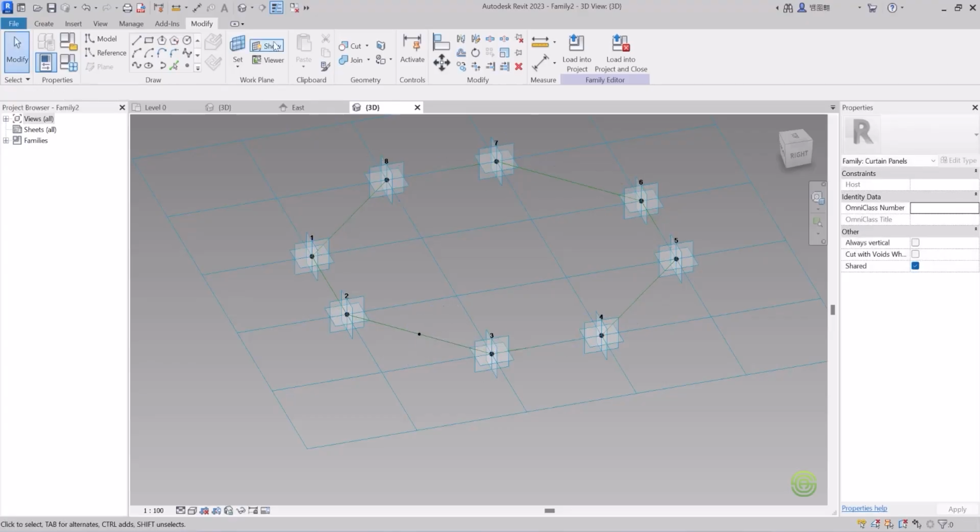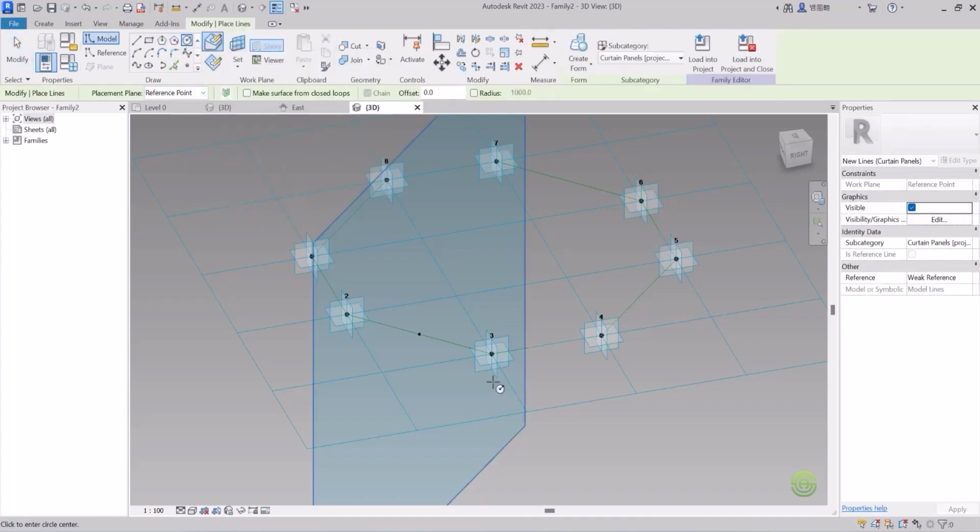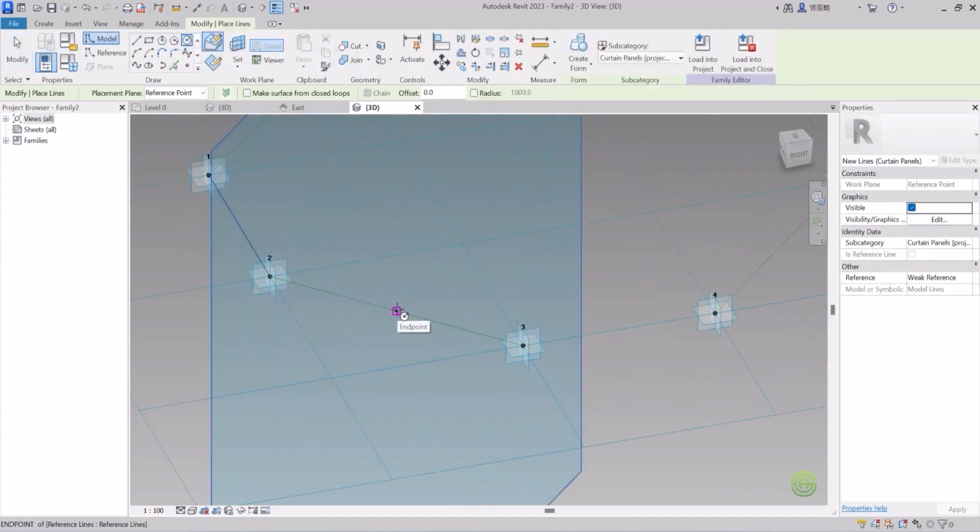After that, to view the work plane, just click on Show. So now you can see the work plane. Now we have to draw a profile. To draw a profile, just select any tool here, circle or hexagon, whatever. I'll select circle here and then I'll draw a profile from that point like this.